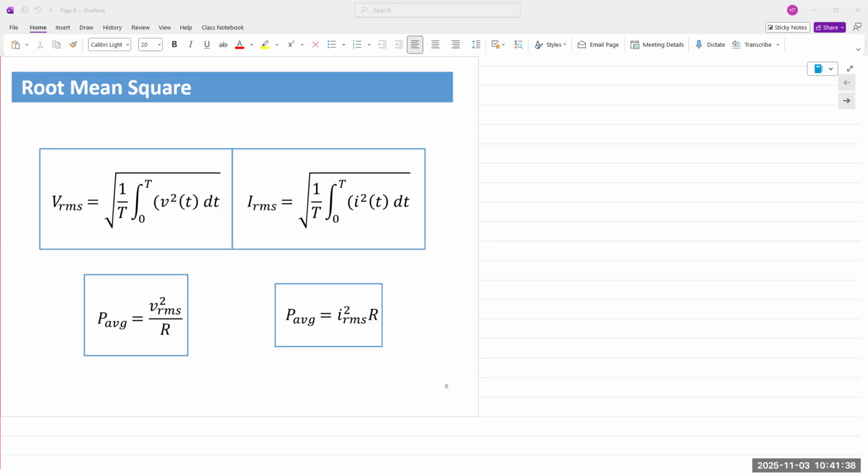If we divide the AC waveform into two half cycles, one positive, one negative, in one half cycle the energy will flow into the component, and in the other half cycle the energy will flow out. This happens constantly. So the behavior of an inductor or a capacitor is completely different when it comes to AC.